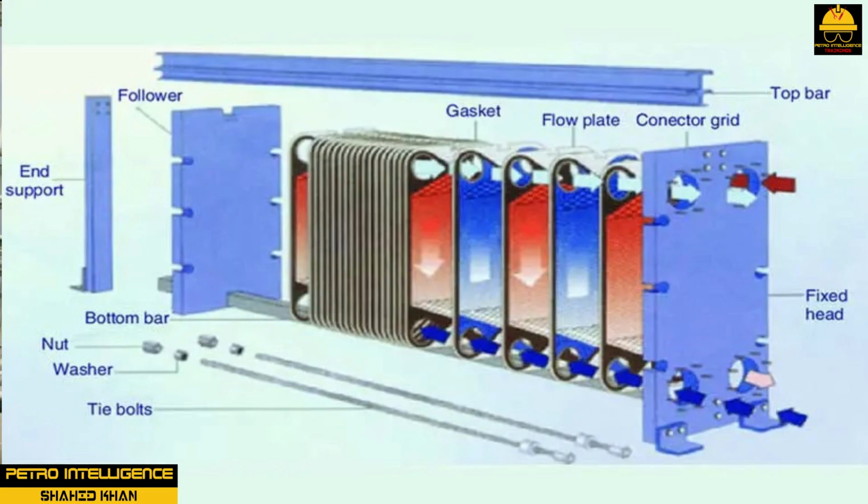Plate and frame heat exchangers are composed of thin, alternating metal plates that are designed for hot and cold service. Each plate has an outer gasket that seals each compartment. Plate and frame heat exchangers have a cold and hot fluid inlet and outlet. Cold and hot fluid headers are formed inside the plate pack, allowing access from every other plate on the hot and cold sides. This device is best suited for viscous or corrosive fluid slurries. It provides excellent high heat transfer. Plate and frame heat exchangers are compact and easy to clean.